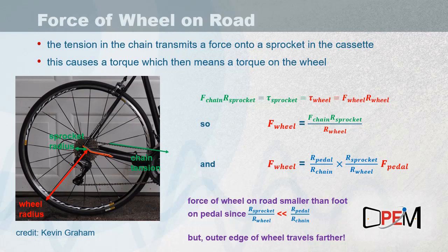And it's kind of the opposite from what happens in the case of a pulley system, where in a multi-pulley system, the object is normally to be able to apply a smaller force to move an object that has a larger weight. And the trade-off by doing that is that you have to move the rope that's ultimately pulling the pulley system and the object up into the air much further than the object is actually raised.